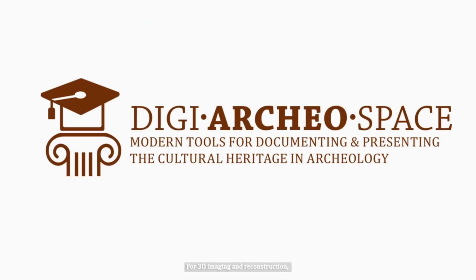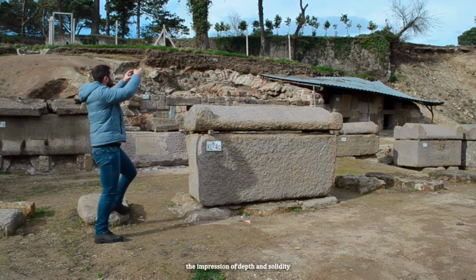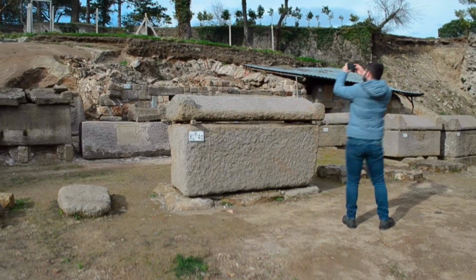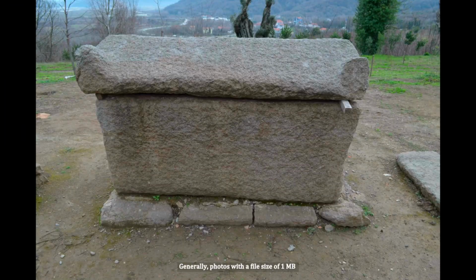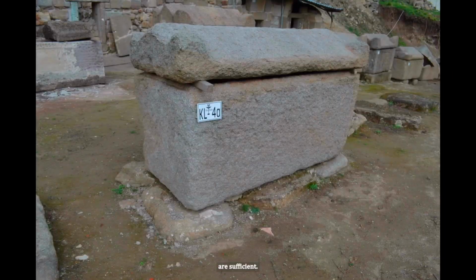For 3D imaging and reconstruction, the stereoscopic photographs of the objects should be taken, covering a 360-degree area. Stereoscopic photographs are images that create the impression of depth and solidity by juxtaposing consecutive photographs of the same object taken from different angles. Photographs of suitable quality can be obtained with a digital camera or a mobile phone. Generally, photos with a file size of 1 MB taken in suitable light conditions are sufficient.